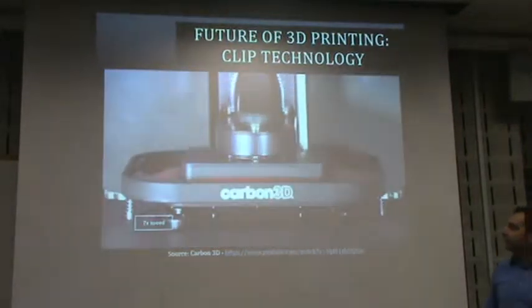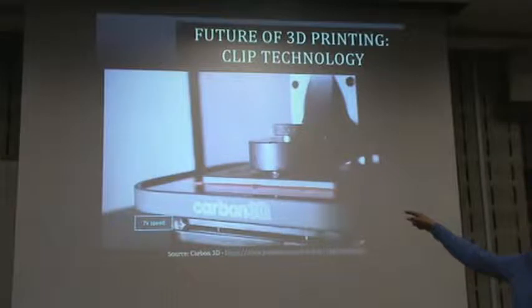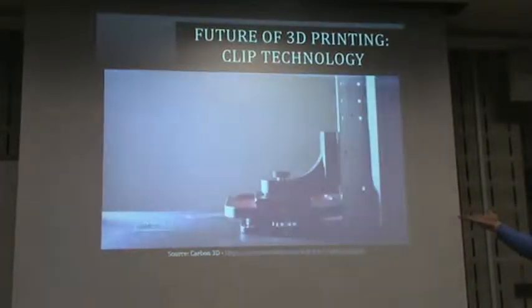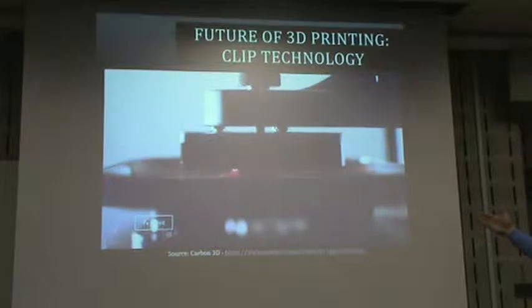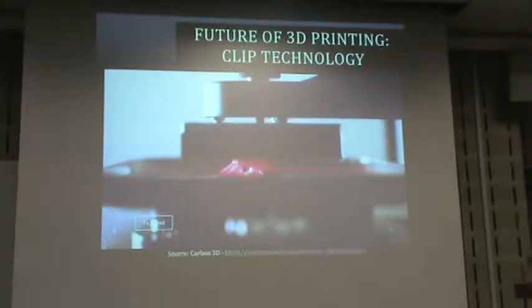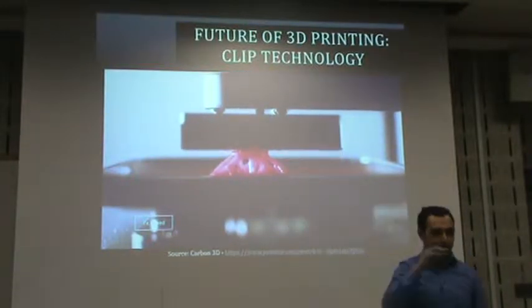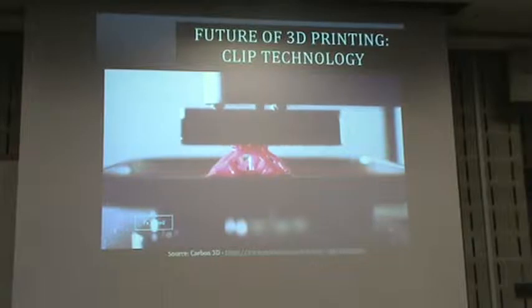Okay, so this is the next generation. I intentionally wanted to have this. This is stereolithography. You can see that it tries to build the model upside down and from a liquid. It's curing it using ultraviolet lasers, and you can see it's trying to print a ball from a liquid. There is a laser at the bottom that only cures the model depending upon what the CAD model is.